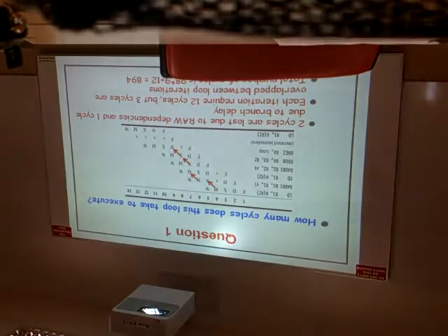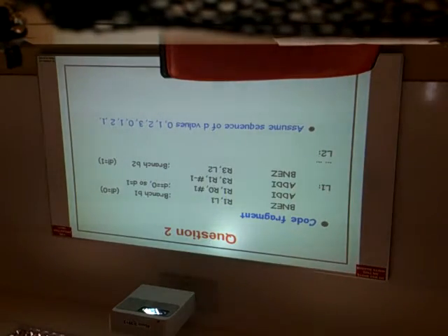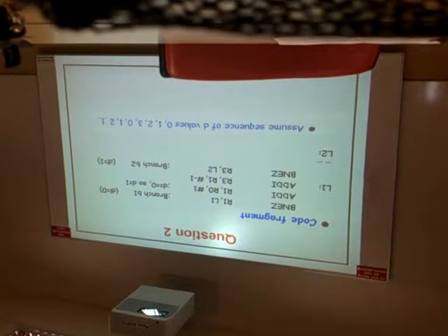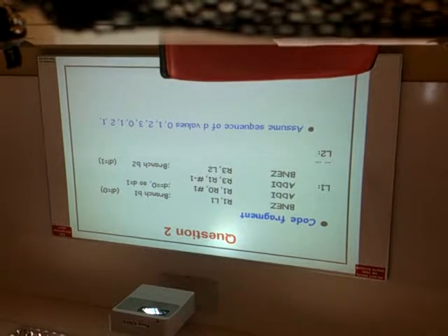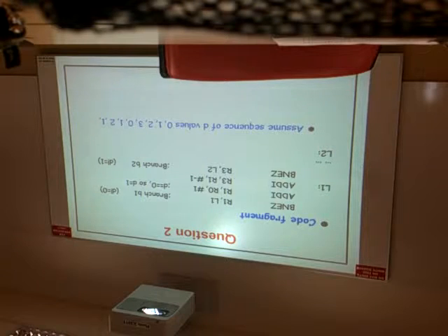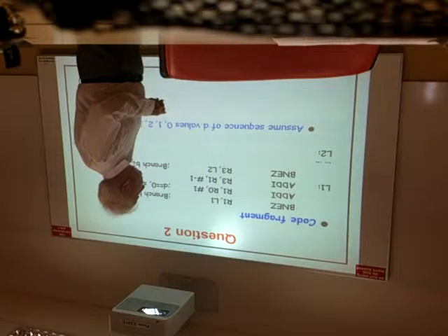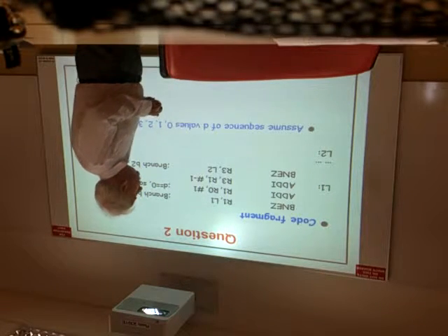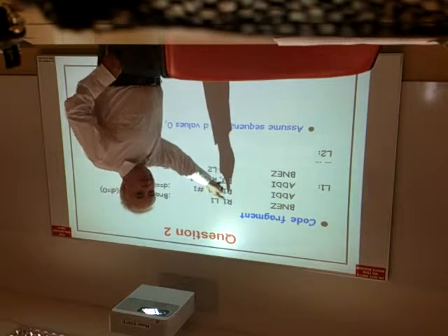The order, I don't know. Some got FDS, some got FS, then some got FD. Because the basic five cycle is fetch, decode, execute, memory, then write back. In order to have this five cycle, you only do one instruction at one time, so you cannot overlap. Like if you fetch one instruction, then you do the instruction at the same cycle of fetching, then you will fetch the wrong data.